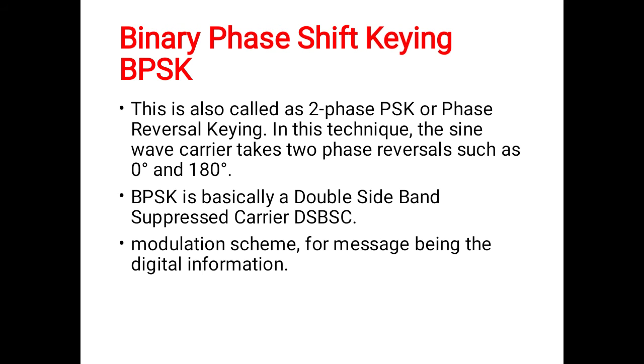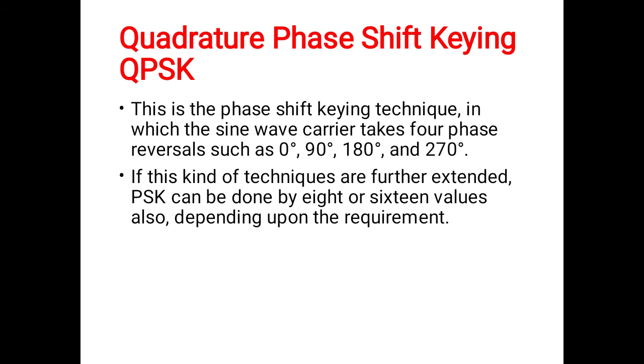In this technique, the sine wave carrier takes two phase reversals, 0 and 180. It is basically a double sideband suppressed carrier, DSBSC, modulation scheme for message being the digital information.